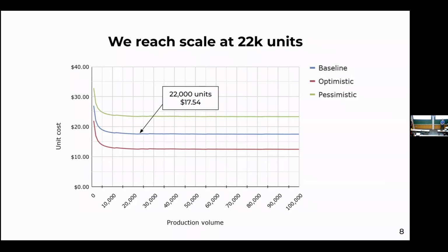And so it's really just the equipment, and do you know which pieces of equipment are at really low volume, unit costs go up? What's the biggest driver of the cost being high at really low volume? For the production? Yeah. For the process? The pick and place machine. Yeah, pick and place machine. That one's pretty expensive. But at high volumes, it goes down to nothing in comparison to the actual material cost. And so in practice, if you were really doing low volume, you would do it by hand, which is probably how you do it in the lab. So yeah. Great. Other questions?